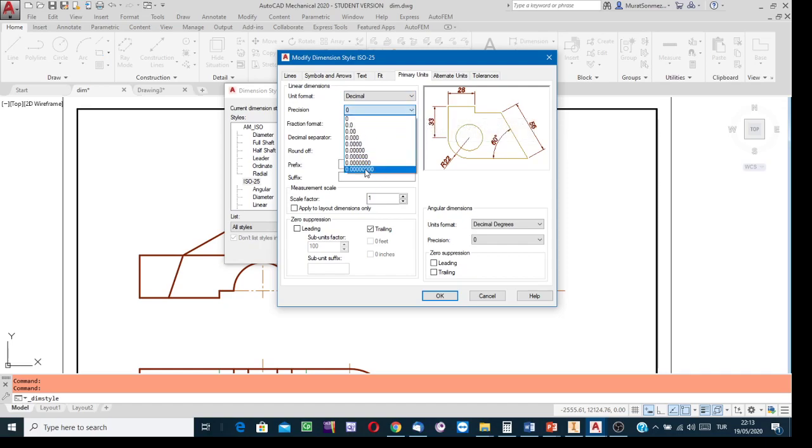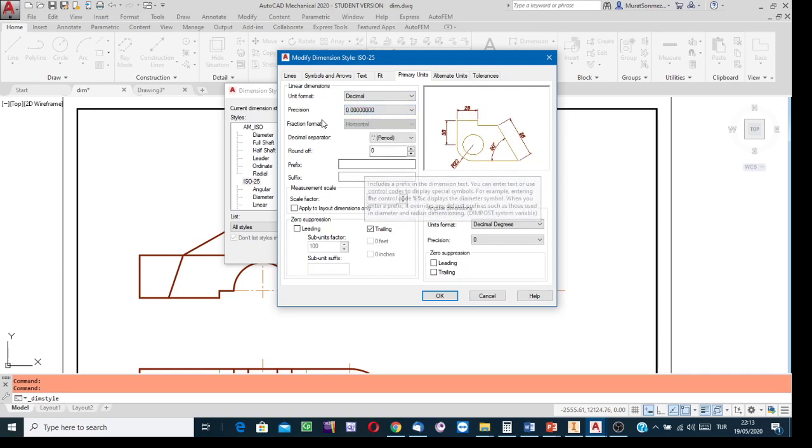If you by mistake, for instance, select this option, saying that it is quite good to show the dimensions with lots of figures at the decimal part, then in Cyprus you cannot find a manufacturer, in Turkey you cannot find a manufacturer. What do you say? The tens, hundreds, 10,000, 100,000, millions, 10 million, 100 million of 1 millimeter is the precision, the minimum distance. Even in the world, in United States or Japan, you cannot find such a manufacturer. Never make such a mistake.